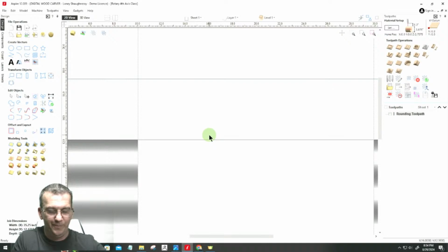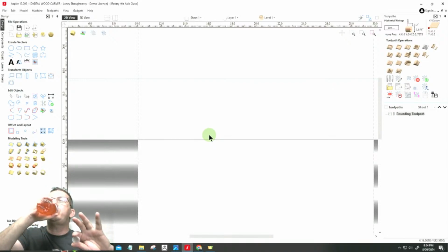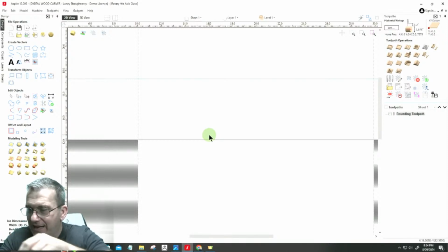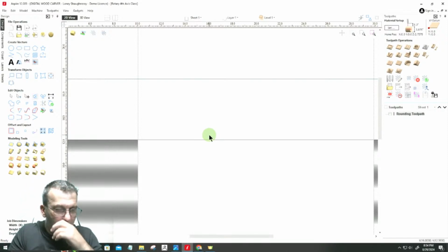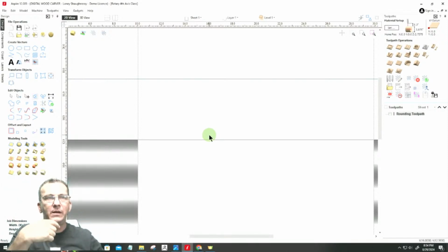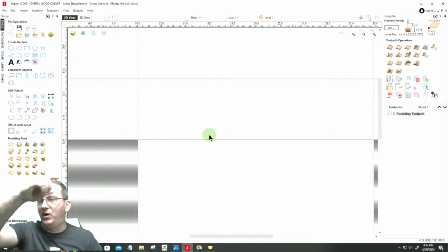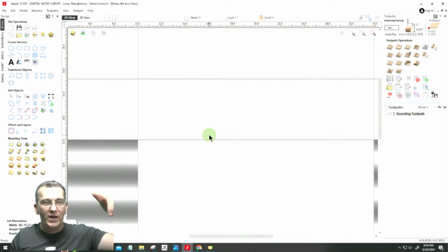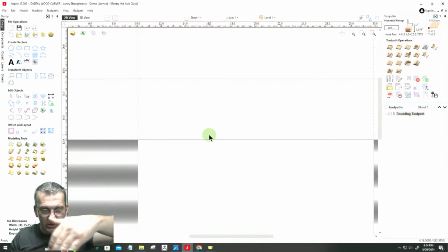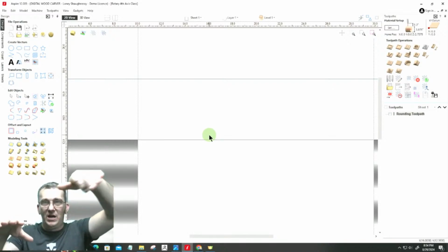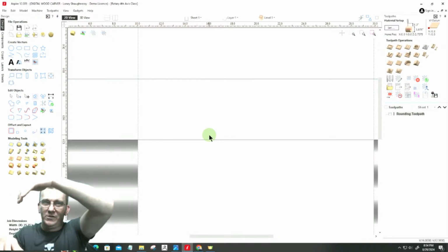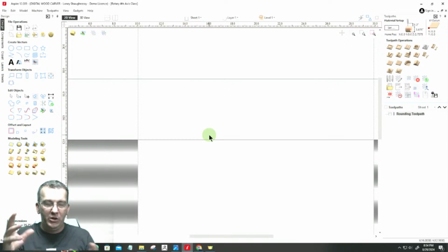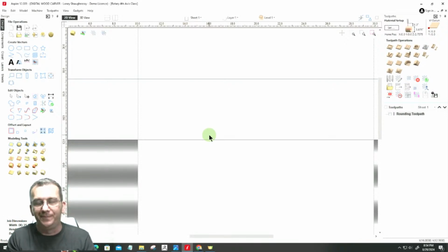But right now, I am creating a 3D model, meaning that my 1/8 inch ball nose, 1/4 inch ball nose, 16th inch, whatever it may be, my one bit is carving that model, all the highs and lows, ups and downs. It's that one bit. I'm CAD machining, computer design machining. I'm 3D model machining.